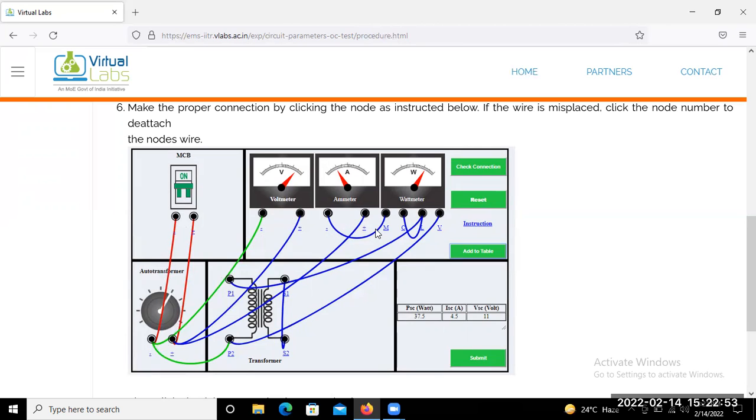So this L and C may be short circuited. Okay, and power is given from this auto transformer to the ammeter, that means the positive terminal. Then the negative of this polarity may be given to the M of the wattmeter, and from V it comes back to the HV winding negative polarity. Okay, and from this point we will connect to the negative polarity of the auto transformer.